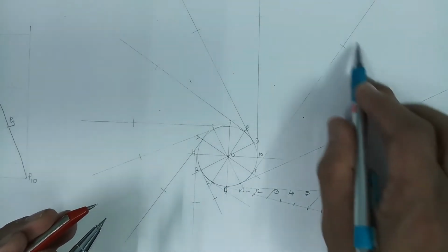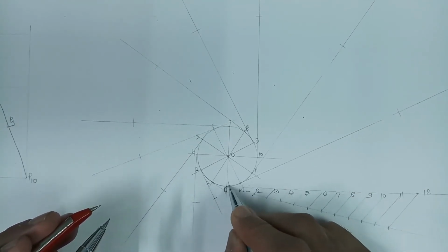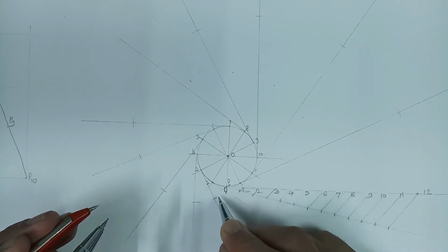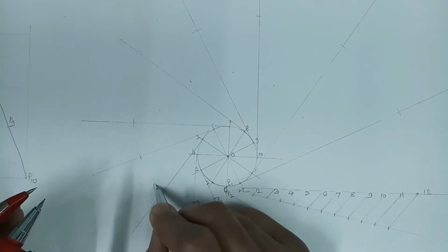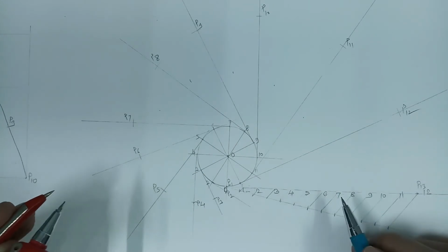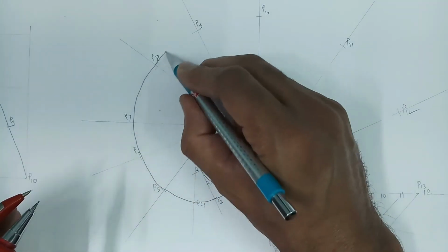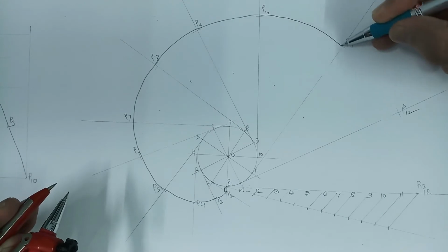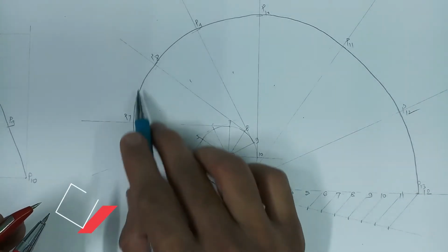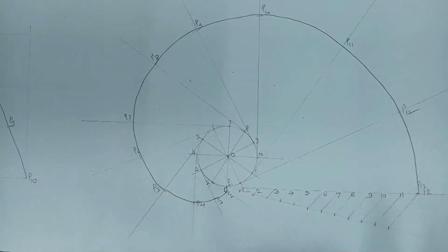Now we have to simply join all these points by a smooth curve. For the purpose of obtaining the curve, we can name the points. Let us say this is point P, then accordingly I can call these points P1, P2 and so on. We have to join all these points by a smooth curve. Again, to save time, I am joining these points by a smooth curve freehand. So this curve traced by these points is called the involute of a circle. Finally, we have to show the diameter of the circle.